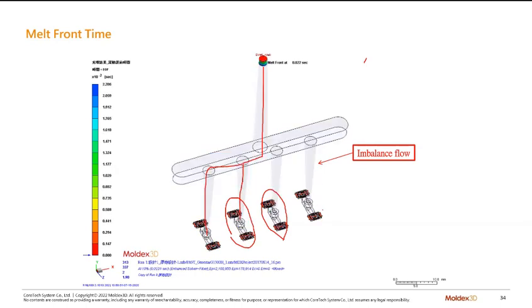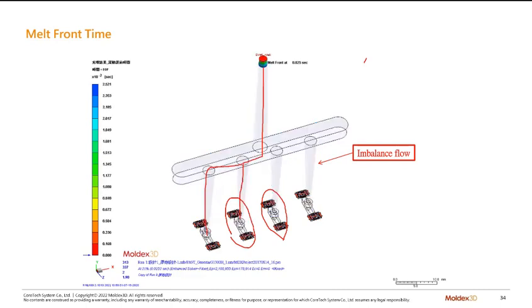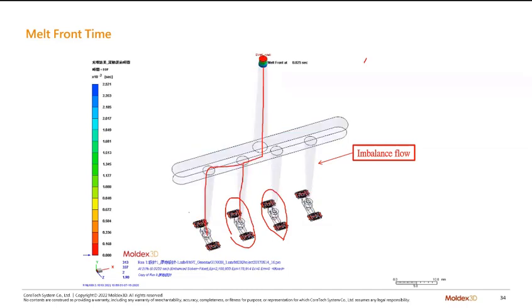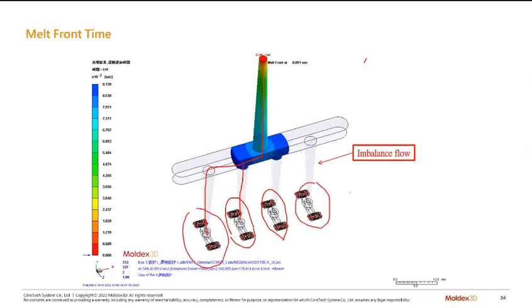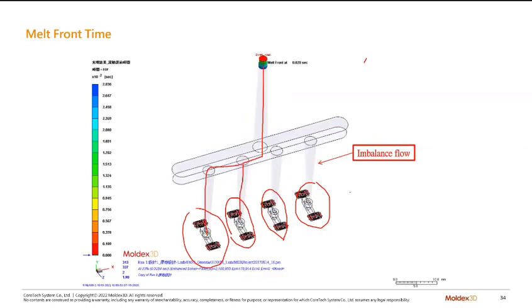And when those two fill completely, it will go into the packing phase, and the material will for sure be at a lower temperature to fill these four cavities.